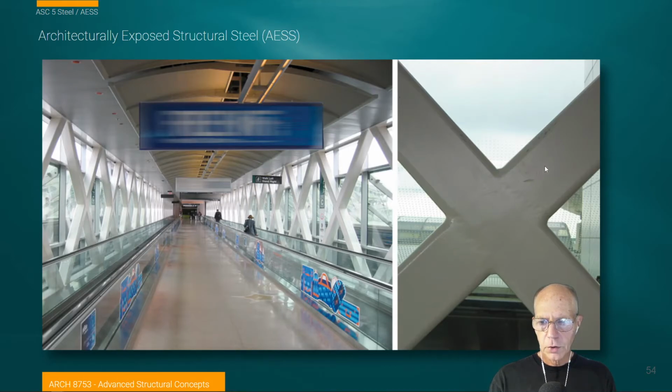So this is an individual element, and on this side it's an individual element. And in order to make these look monolithic, this was fillet welded, and then the fillet weld was ground down until it was flush to the surface. So the overall appearance, if we look down the hallway here, is that these are really very pristine looking monolithic objects. But on close inspection under certain light, you will see this kind of a defect.